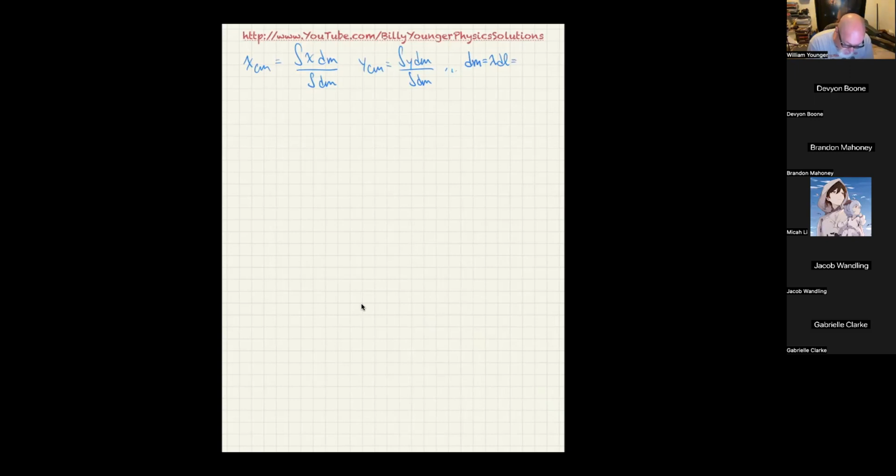If you have a two-dimensional object, which would maybe be like a sheet of plywood, which rarely has even a whole inch of thickness. It's much more normal to get on the order of 3/4 of an inch, even for the stuff for your floors. And then it's 4 foot wide by 8 foot long. So that's really way bigger in two dimensions than it is in a third. In that case, you would use sigma times dA. Or if you truly have a three-dimensional object, then you would use rho times dV, where V is the volume.